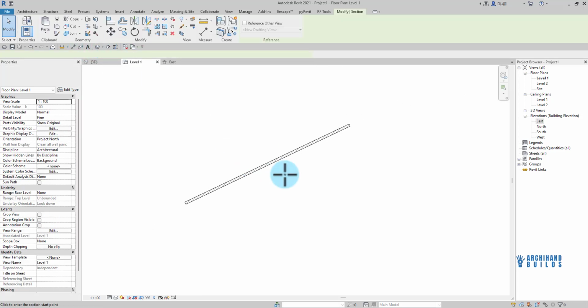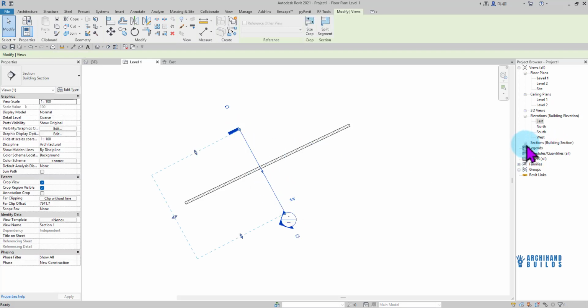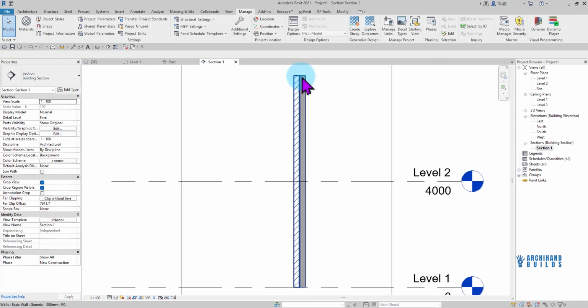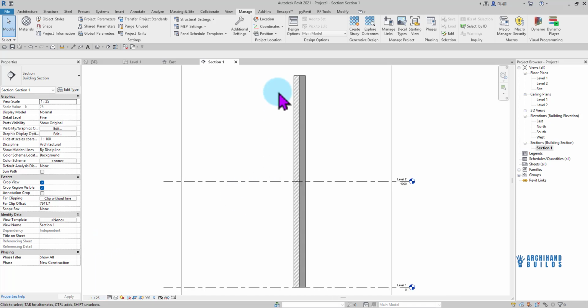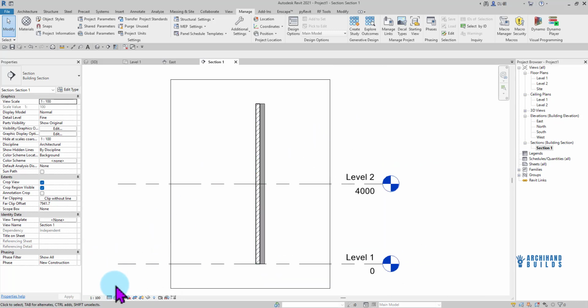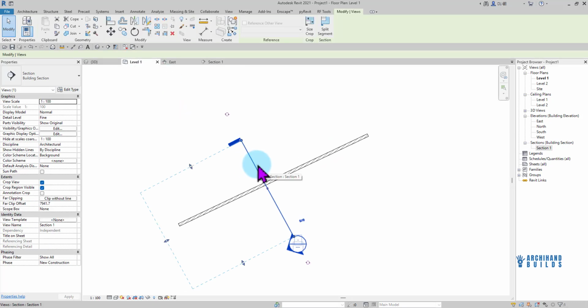All right, so I'm going to cut a section through our wall in there. I'm going to cut a simple section, click in there, and you can see we would have to change this to fine, and you can see we have our cut pattern line in there. With this, when you change the scale, it also changes the number of cut patterns we have in there. So that's one thing you need to have in mind as well. So I'm going to get back into 1 in 100, which is the default scale, and then delete my section line.